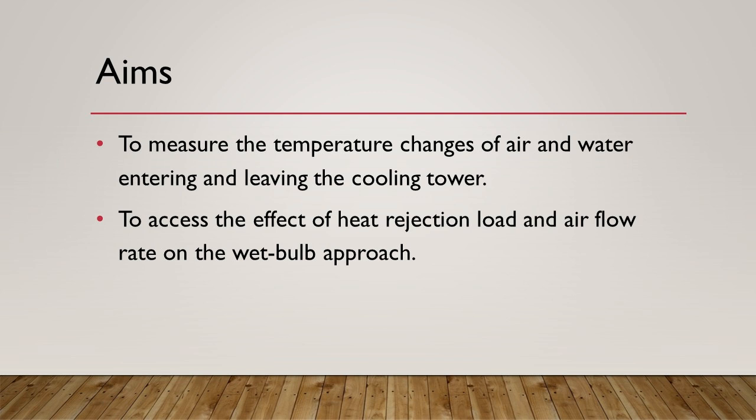In this experiment, students would measure the temperature changes of air and water entering and leaving the cooling tower, in order to assess the effect of heat rejection load and air flow rate on the wet bulb approach.